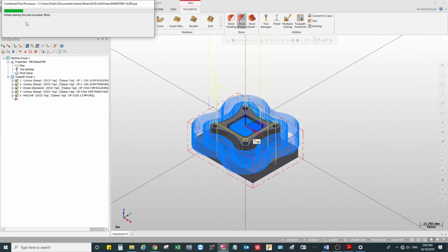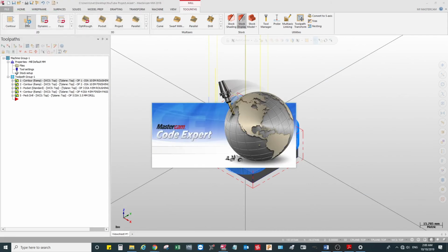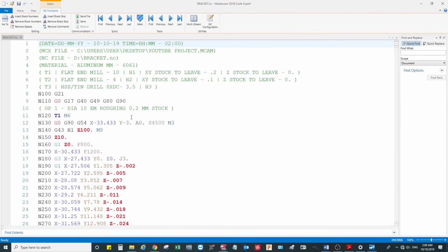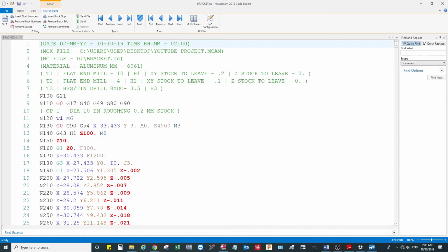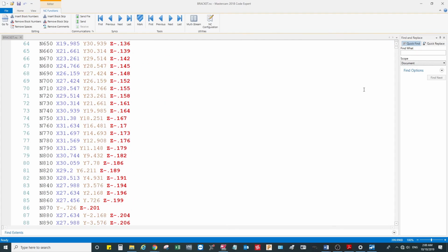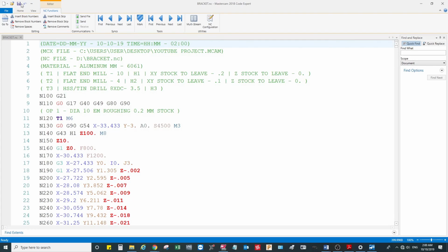It's asking me for some other information in here, the linking parameters. So I'm going to go and click 100 millimeter with absolute, and then I'm going to click on use clearance only at the start and the end of the operation. That becomes really easy and saves you a lot of time. The retract absolute command. Yep, so it's all good.